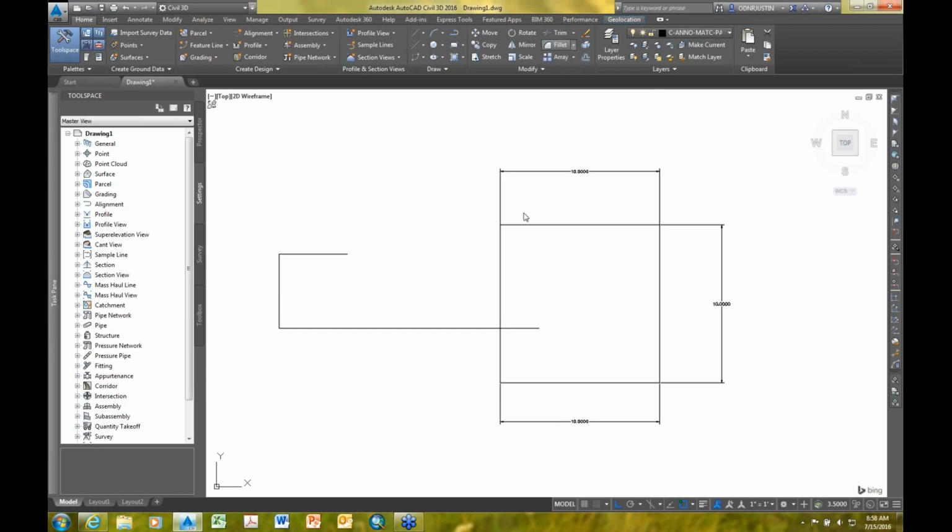If I use the trim tool and I want to get rid of this part that I drew that goes into the box, I can click on my box and that becomes the line with which the other line will be cut. Click enter, and I'm going to trim this piece off right here, and it's going to show you it went in light gray, so I don't need that. Let's cut that. And then let's take the other one and do an extend. Same concept. Just going to click on the box, hit enter, and it's going to show me how I could extend that line. Okay, there you go. So I made a little chute off of my box there.